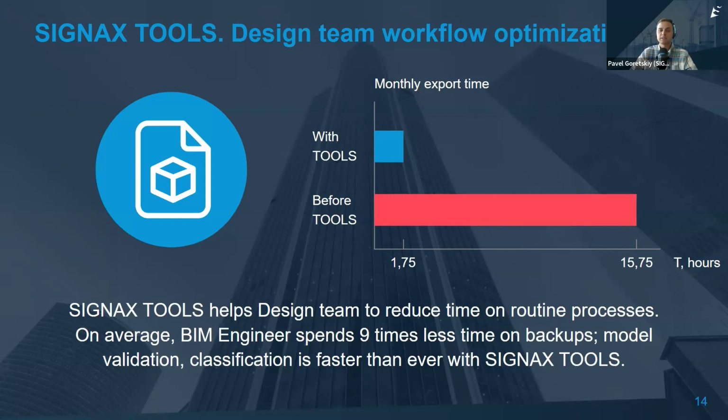Additionally, we will delve into clash detection for multidisciplinary coordination and check the presence and completeness of properties according to EIR requirements. Finally, we will discuss how to import the check results back into Revit for automatic model validation.